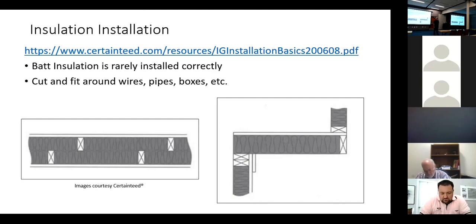When I tell people in our office my best practice, it's don't put it anywhere it's going to get really hot. That's when it's going to start to degrade and crack and have issues like that. But usually if it's on the back of a ventilated drainage plane or something like that, it's pretty good. And we are seeing a lot of it sprayed on the underside of roof decks. So maybe that's not the best. We did a project recently where we used Dura Vent between the top chords of the truss to create that ventilated airspace, to ventilate the roof deck. So you still have soffit and a ridge vent, and then spray foam on the inside of that.